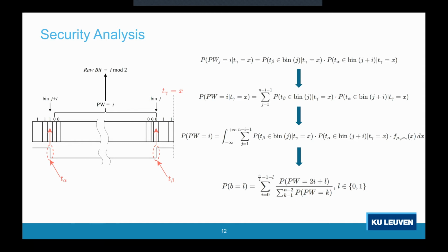Note that to precisely determine these probabilities, we have to know the variances and means of all 3 edges, as well as the propagation delays of individual bits. The min-entropy, because of our independence assumption, can be directly calculated from these binary probabilities. So at the end of our security analysis, we got the expression for the mean